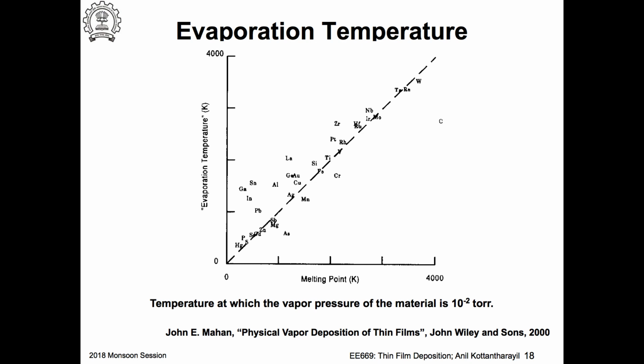These are things that you find in the lab where people do a lot of deposition: titanium, platinum also, chromium and so on. And this part is a little less. If you want to deposit this, then the process of preference is sputtering, where you don't have to melt the material. If I want to deposit tungsten, I need to find a crucible which can hold it, and that's the problem.